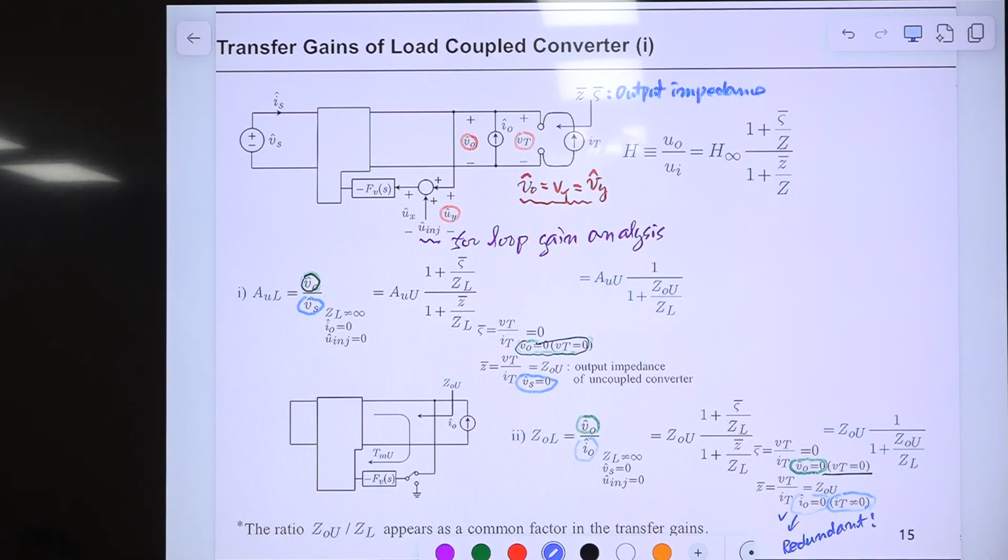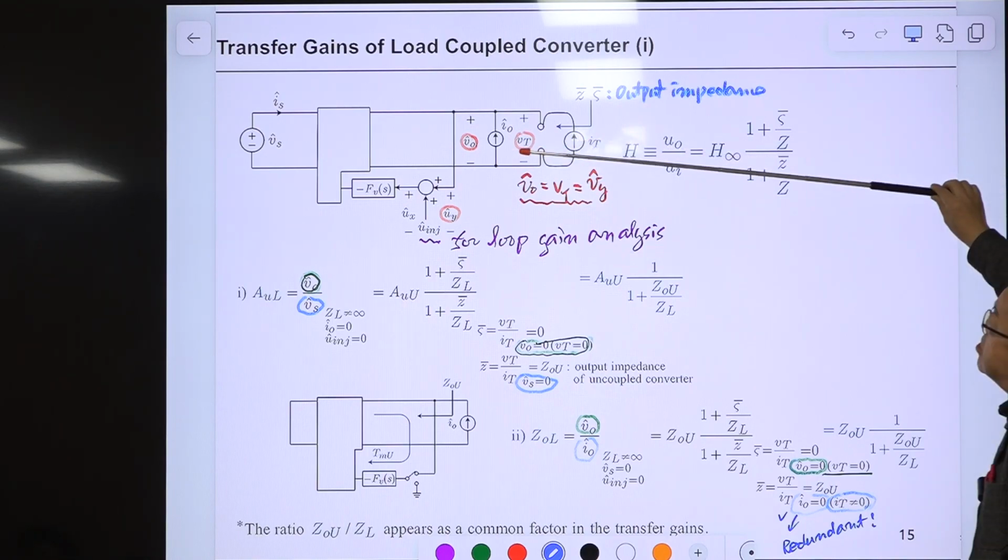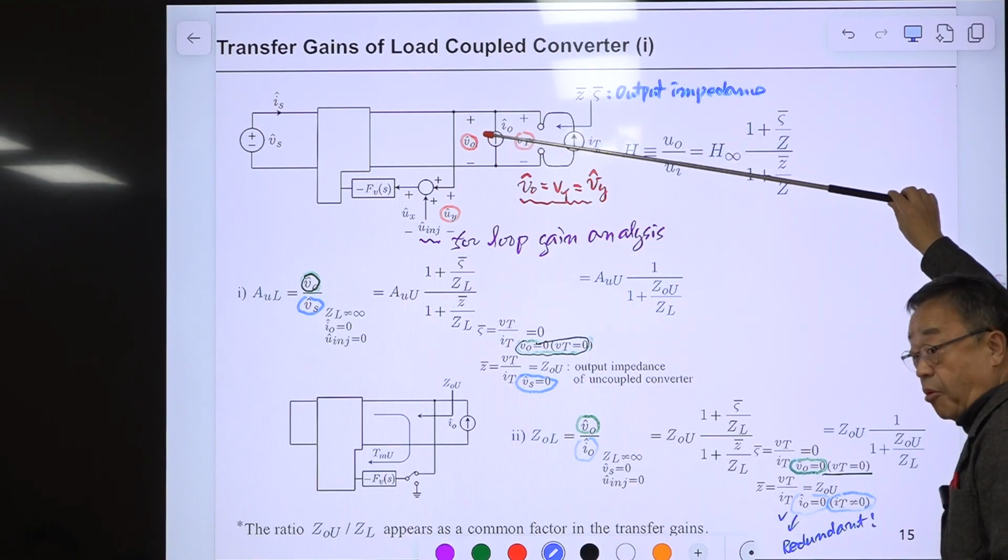If you are interested in a particular transfer function, so once the input is 0, and next time the output is something like that, then you can evaluate this, right? But here G was on the output side of this converter. So what you are seeing is basically the output impedance, because you are looking at this system at the output of this converter.